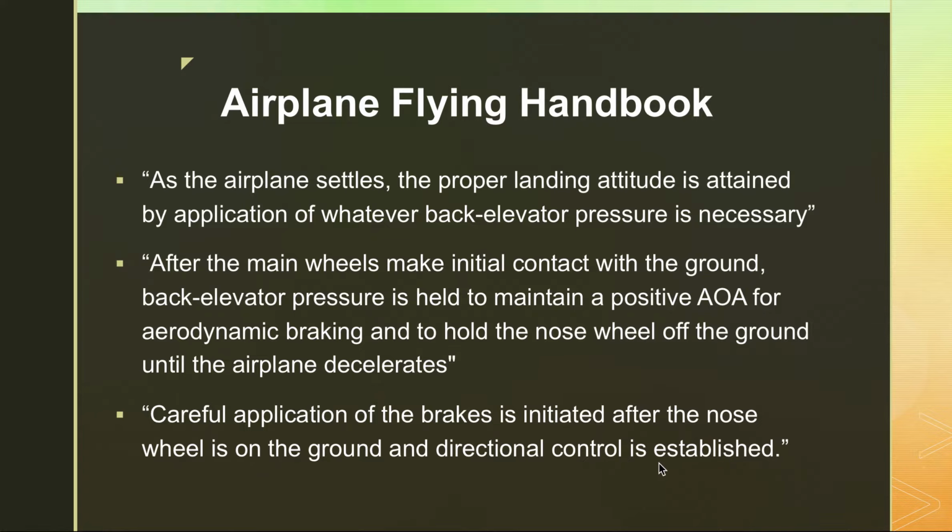So generally the way I land is I land on the mains and I keep my back pressure. I try to keep that nose wheel off the runway as long as possible. Eventually you have full up elevator, and the nose wheel drops to the ground anyway. Make sure that you have directional control maintained, and then and only then can you worry about moving your feet up the pedals and applying the brakes. Nice and softly.